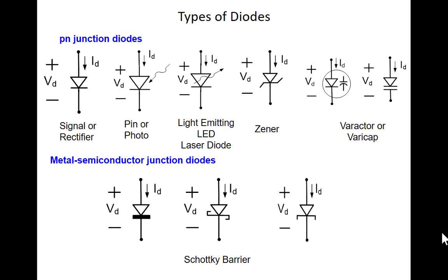One other comment about some of these other diodes. If you go back to the work of Shockley and what was the other guy's name? If you go back to the junction diode, they were interested in using it as a rectifier. And a lot of these other properties, the fact that you shine light on it and the reverse current changes, we don't like the large reverse current normally. You put current through it and the light comes out. Those would probably be considered to be undesirable, and the capacitance across it changes, those would probably all be considered to be undesirable properties of the original diodes.